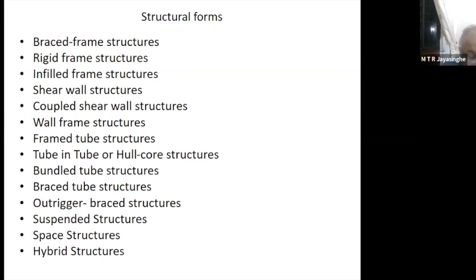Deck material has a thickness of 0.7 millimeter. When you are using deck material as reinforcement, you must use a properly manufactured deck material with sufficient corrosion control. Otherwise, you will find a huge amount of problems.